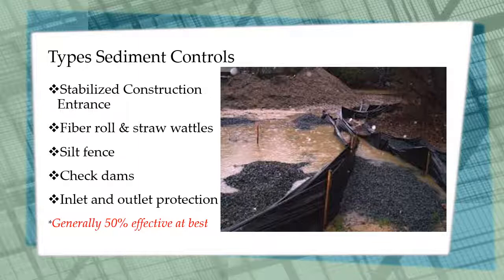Relative to erosion control BMPs, sediment control BMPs are generally about 50% effective. Erosion control BMPs are more likely to be 90% effective. Therefore, erosion control BMPs should be your first line of defense.